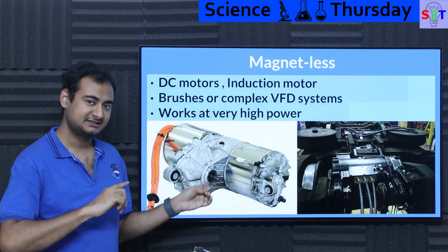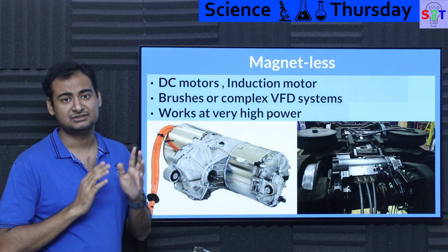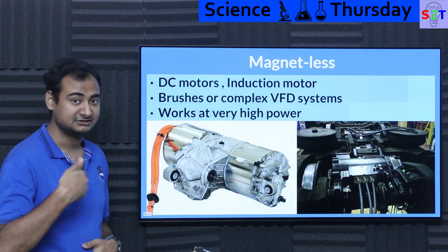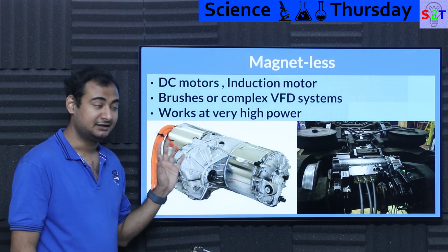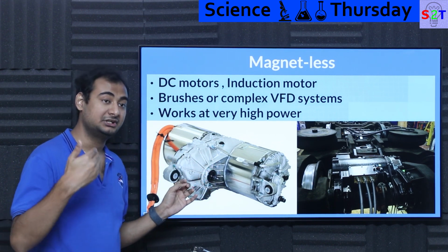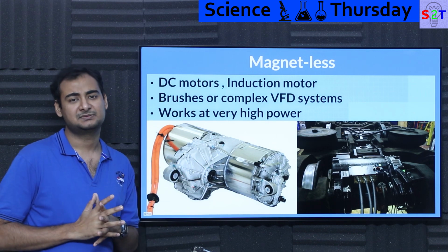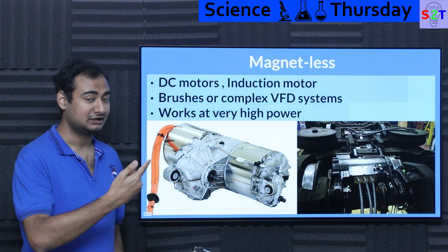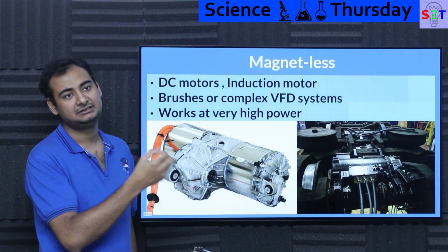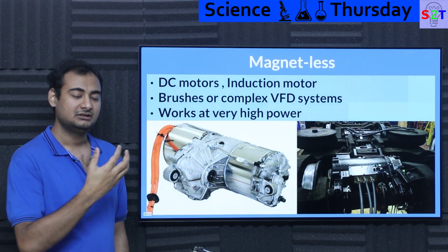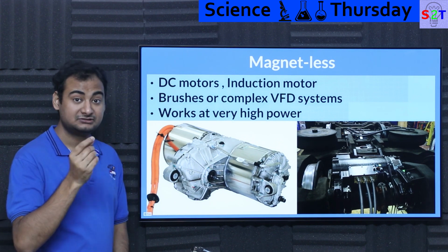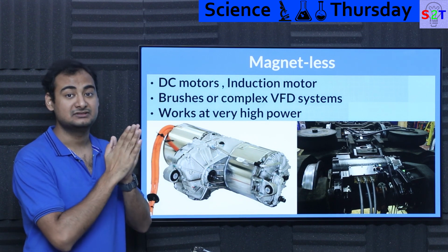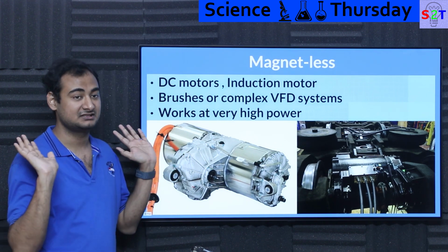Now be mindful, it is an induction system utilizing VFD, so it's not as efficient as if it had a permanent magnet or some other electromagnet at its rotor, but it does work. And you are recovering some of the energy that you put into acceleration. Generally people are expecting around 30% efficiency. So let's say you put 1 kilowatt of energy into accelerating your car, you're supposed to get around 0.3 kilowatts back when you are braking. That 0.3 kilowatt is saving your brake pads. That amount of energy is no longer dissipated by your brake pads. The brake pads are like, I got this.